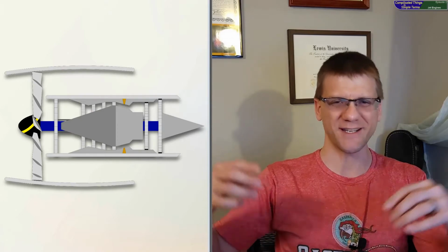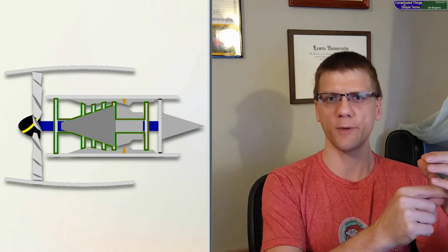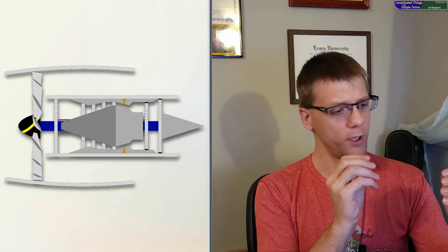I referred to jet engines as having just one moving part, and that is, to be fair, an exaggeration. The main part is that one rotating spool. Well, in order to make engines even more efficient, we now use 2 or 3 spool designs, and all that means is that the big fan on the front is on a different spool. It's on a different rod through the center of the engine and therefore can spin at a different speed. The geometry by which that's set up is clever and relatively simple. So we have the one spool at the center, and it has the, relatively speaking, small fan, the compressors, and the turbine at the back. The air comes in, gets compressed, mixed with jet fuel, explodes out the back, turns the turbine, which turns the little fan.